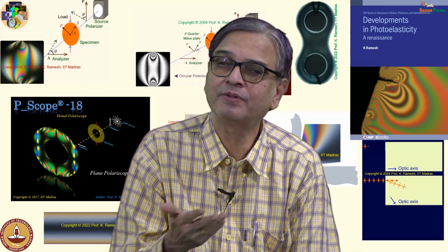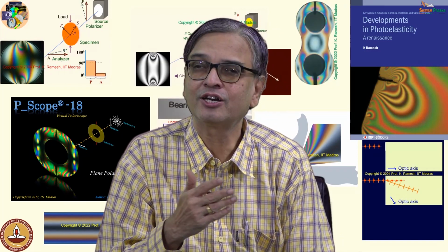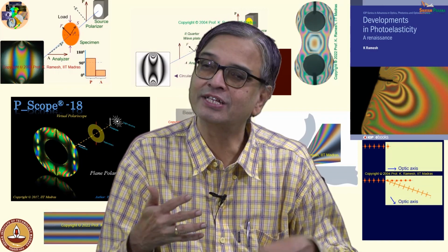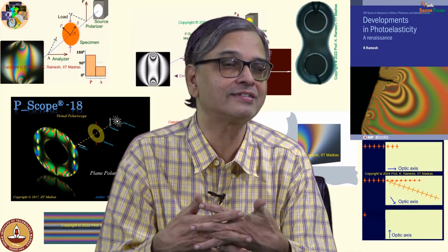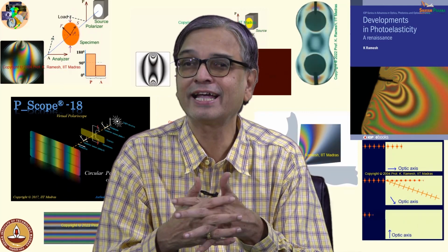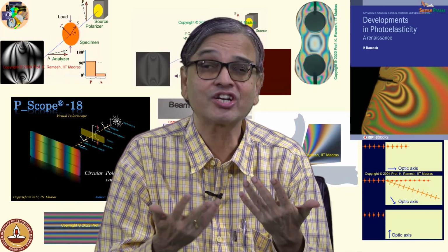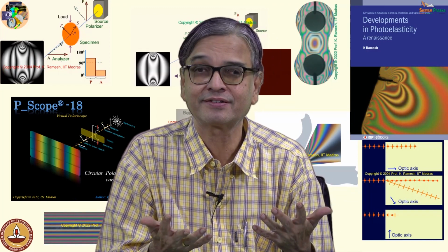And with the long discussion we had on stress, we understood that the state of stress at a point is a tensor of rank 2. So, there is a happy everlasting marriage between refractive indices and stresses. That has helped you to visualize the stresses which otherwise you could not see. You could only see deformation.